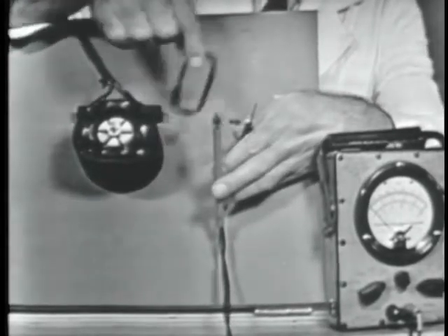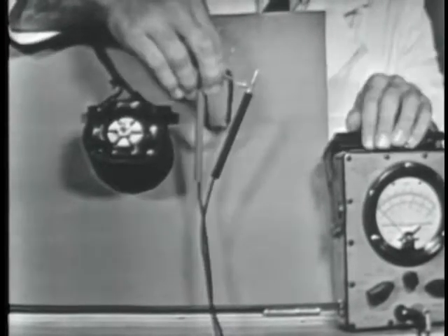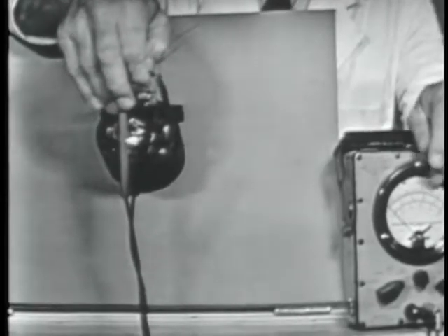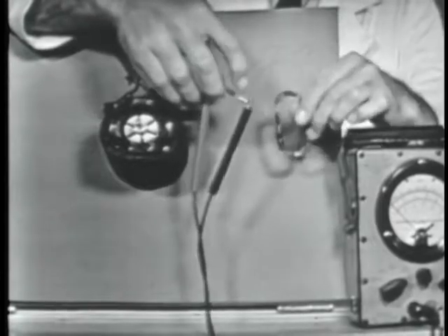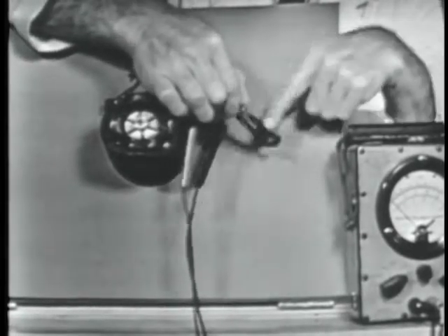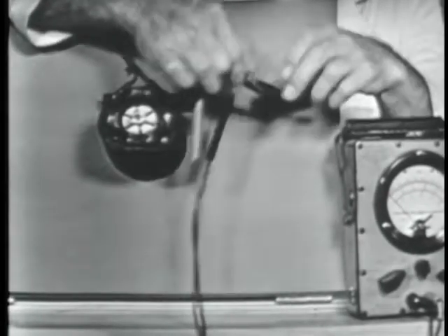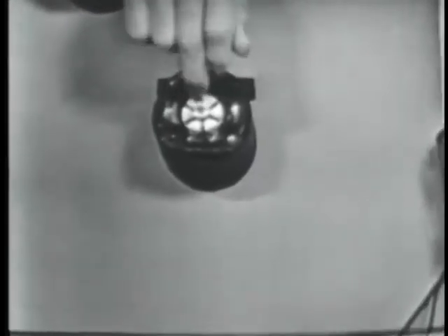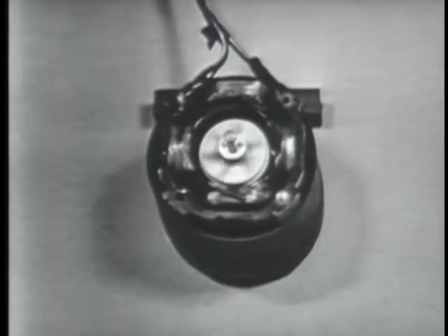Okay, and we proved that with this little loop of wire, the resistor and the PSM6. We put the loop in the field windings, and the PSM6 showed us that we did have a voltage induced into the loop, causing current to flow. Once we had current flow, we know that the loop had to become magnetized and exhibit a north and a south pole. And once we get it magnetized, it has got to follow the rotating magnetic field. Which brings us to item 5, which I believe you can have.